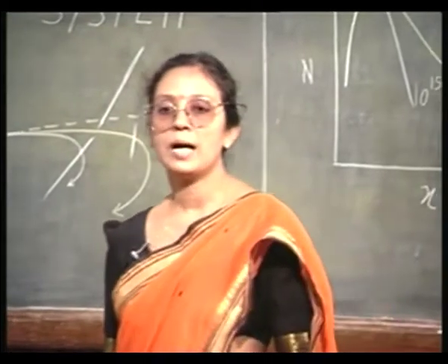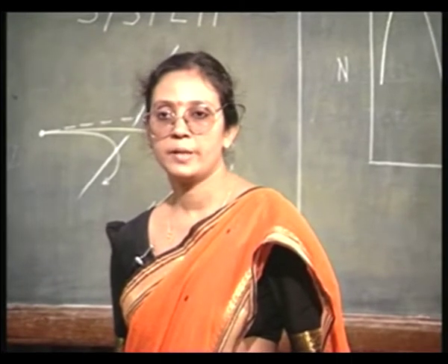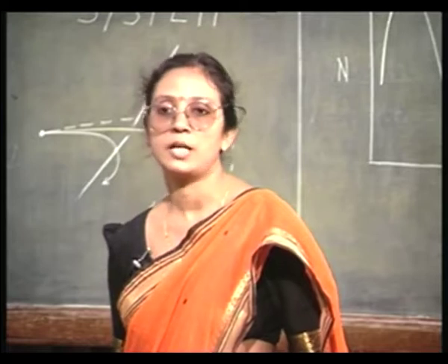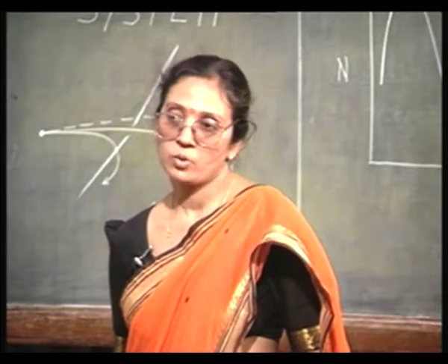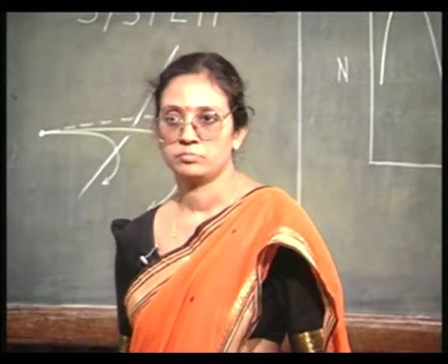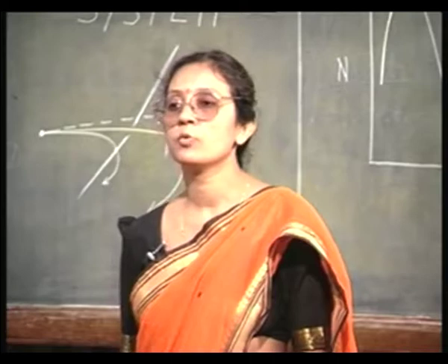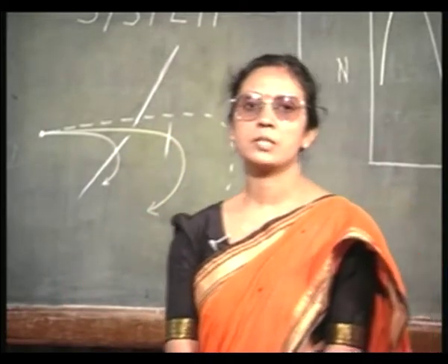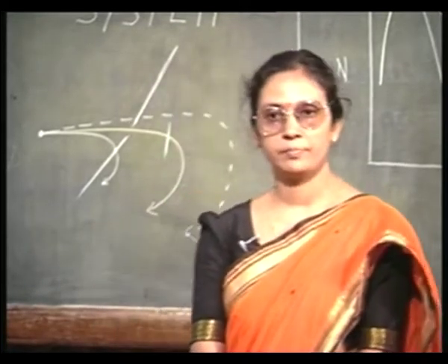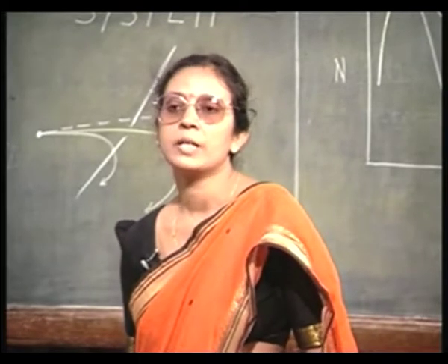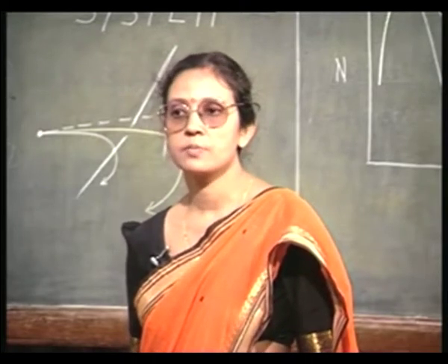So, now you have a damaged region. Depending on whether the incident ion is light or heavy, and the dose is small or big, you have different extents of damage. And you know how to estimate the extent of damage also. For us, the most important factors to estimate this damage are the changes in conductivity, mobility and lifetime. Now, we have to rectify this problem, which is called the annealing of damages. Damages must be annealed out.